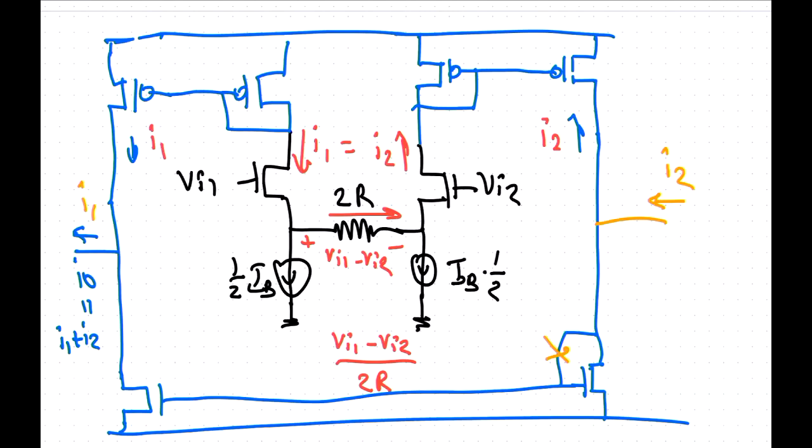So whether I put this connection in or not, I get a single-ended transconductor if I put it in. If I take it out, I get a differential transconductor where the differential transconductance is the same as what I had before. So I need to have common mode feedback if it's differential, obviously, and all that sort of jazz. And I probably want to put cascodes on at the output.